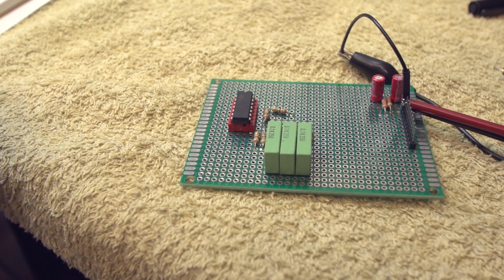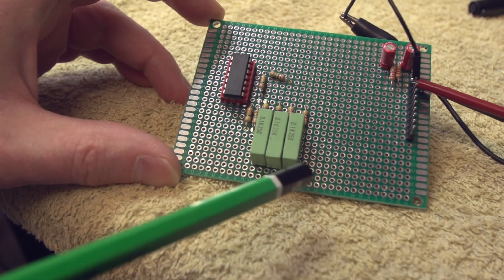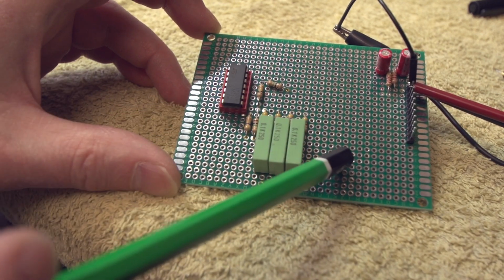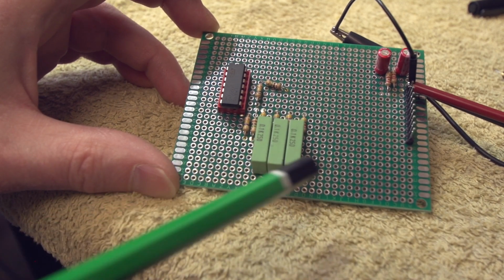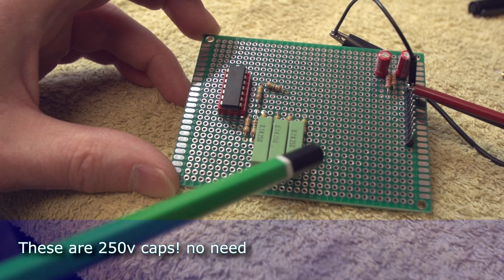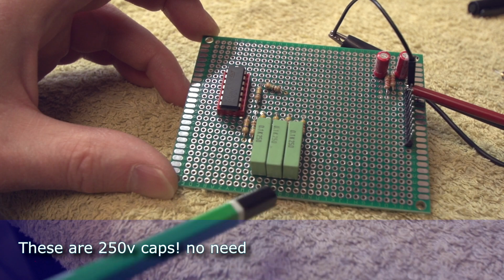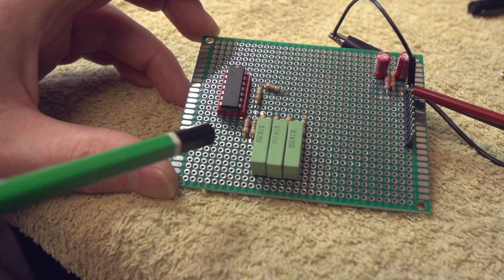This is the oscillator, CW ident oscillator. So the board's not finished. I've still got this area here to populate, which is going to be for the 4066. I've got ridiculously big capacitors in here, physical size, I mean big capacitors. They just need to be 100 nFs. These are all I had lying around, you know, so without getting into surface mount. So basically I've just stuck them in.